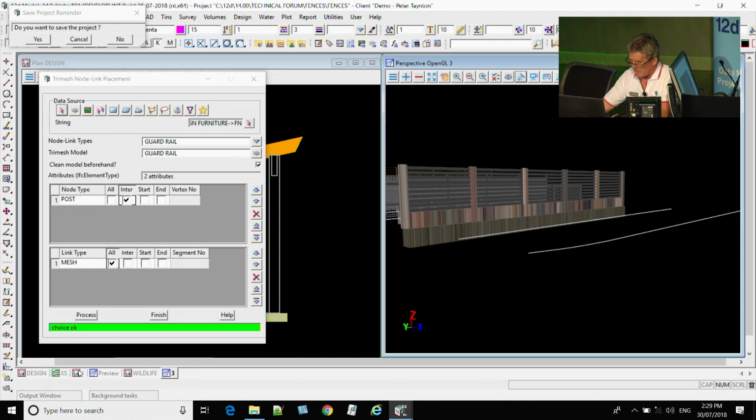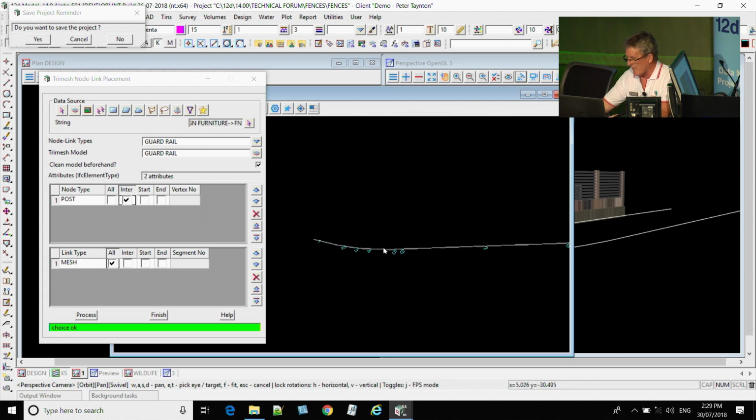But if I look at my plan view, it's a guardrail, and there's a couple of points that I don't really want to post at, okay? Because the reason why is that it's a W beam for a normal guardrail. So I want the beam to look nice. The string that represents the beam itself, I want it to look really good, right? Not too segmented, but I've got more vertices than I do need.